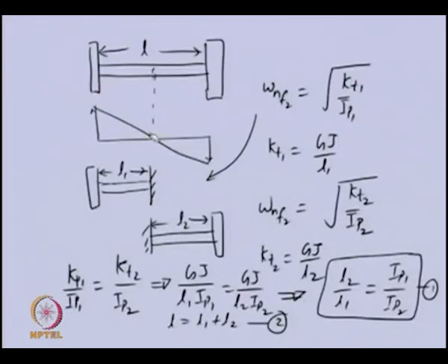So with this procedure, we can get the node position, which is very important because here even though angular displacement is not taking place, stresses will be maximum because on either side of the node we have angular displacement opposite to each other. So maximum stresses will be more here. So we considered a two disk system.